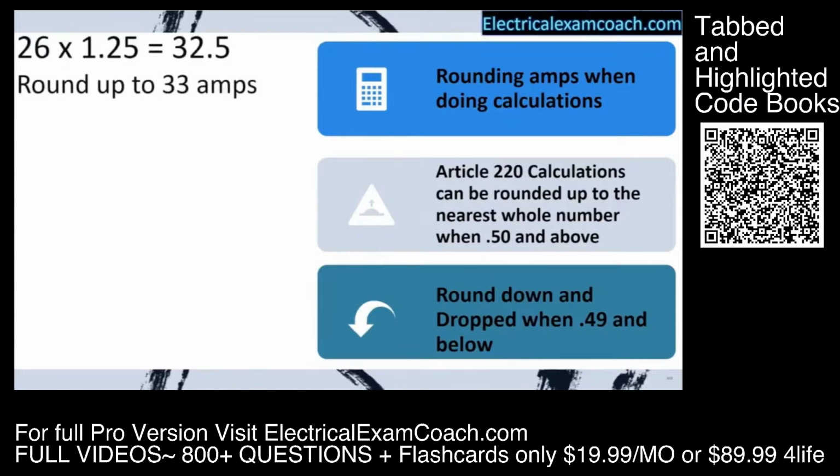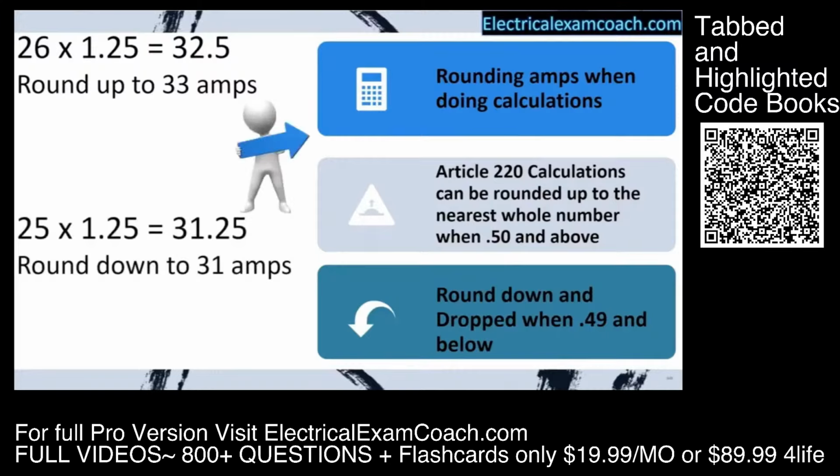So let's imagine we have this scenario of 26 amps, and after we do all of our math, it equals 32.5 amps. Well, in this case, we're going to round up to 33 amps. Now let's imagine we have a similar scenario, and when we get our answer, it's 31.25. Well, in this case, it's 0.49 or less, so we are going to round down in this scenario. And that's how we're going to deal with all of our numbers in load calculations.